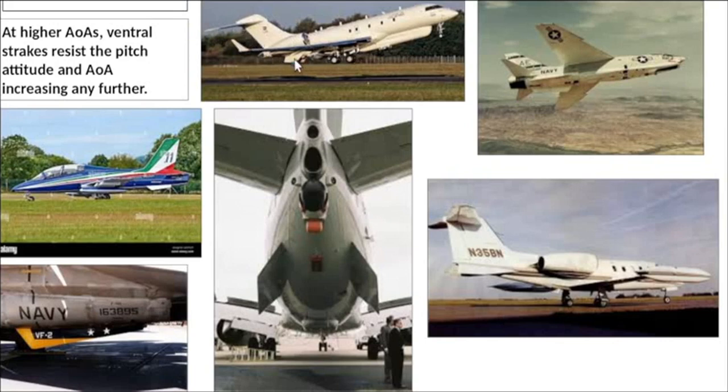So they really don't want that. That's why they have these strakes on the airplane. Also, these two airplanes have a stick pusher, so it kind of behaved like MCAS did before they've updated it, putting the nose down for you to avoid having a bad day.